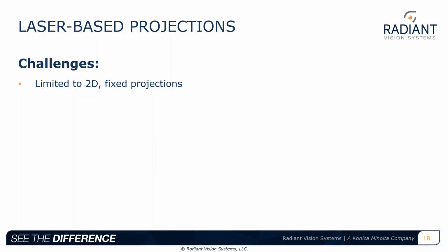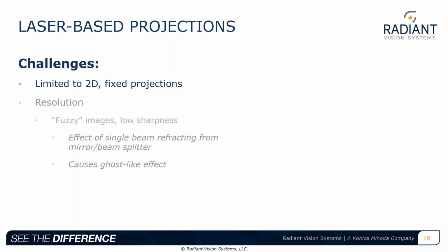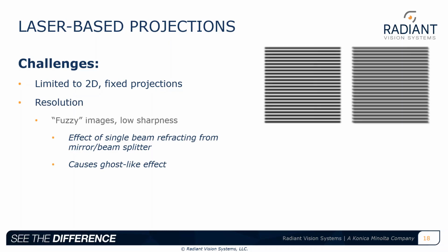However, there are challenges with the technology that exists for lasers today. Because laser technology uses a single beam source to produce its images, the refraction of this light directed toward the windshield causes relatively low clarity compared to other head-up displays right now. This can result in low clarity, fuzzy images, low sharpness, and a reduction in resolution. One of the other things we're seeing when we talk to customers working with this technology is that they see a large deviation in their technology in regards to ghosting effects. Ghosting is something that all head-up displays suffer from, but we're seeing large challenges with laser technology at this point in time.